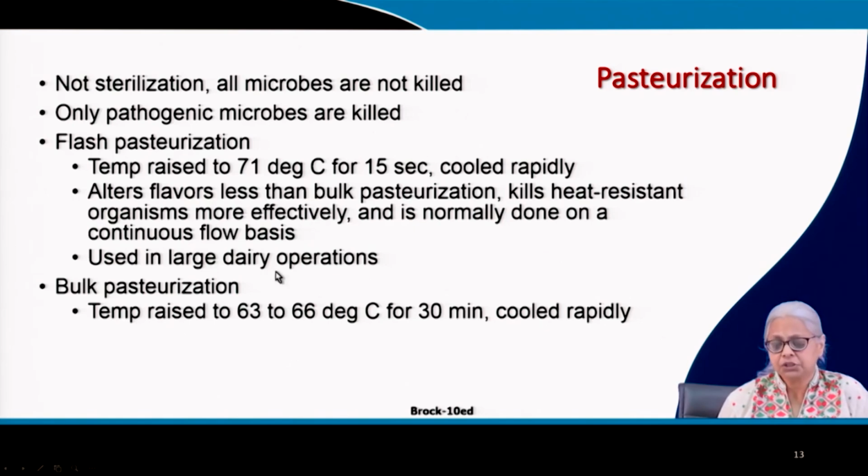This is used in large dairy operations, and when you have bulk pasteurization, the temperature is raised from 63 to 66 degrees centigrade for 30 minutes and then allowed to cool. So this is done, like I said, again in large operations to pasteurize large amounts of material.